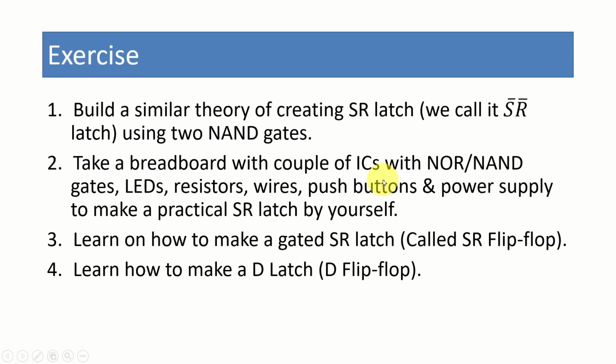And it's a good time to analyze the S bar R bar latch and see how we can set it, how we can reset it, how we can make it into a remembering state or memory state, and whether there are any invalid situations. You should be able to analyze it by yourself now, and then refer to some tutorial and see whether your understanding is correct.